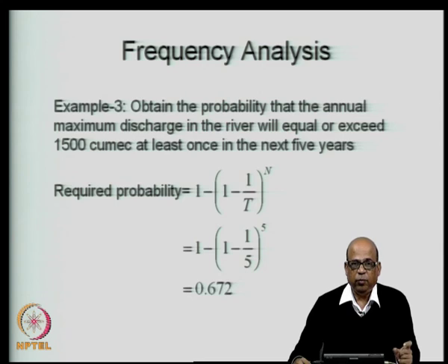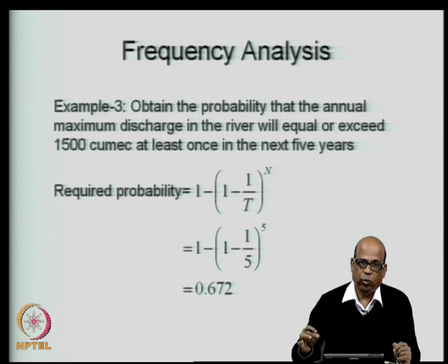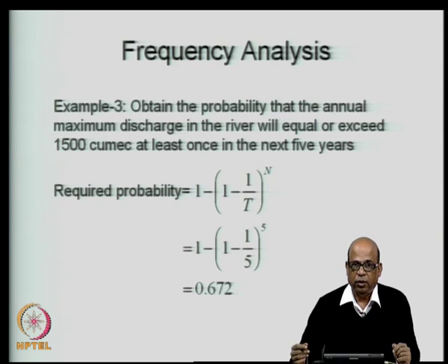The requirement of independence may be ensured by looking at the annual maximum series or annual minimum series, where every year you pick up one value out of a large number of values that have been recorded, be it the maximum or the minimum. Then from year to year you can assume them to be independent.